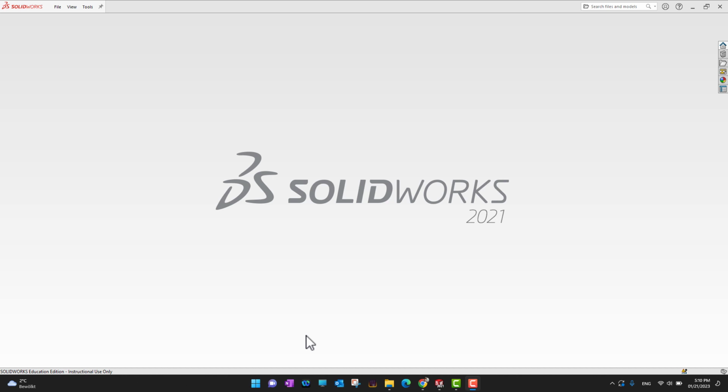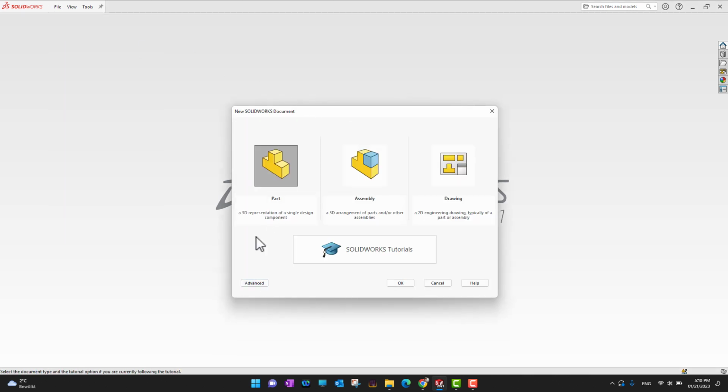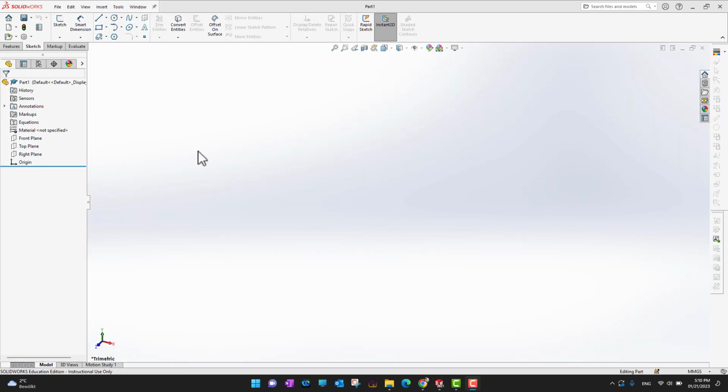Specifically in this video, we are going to design our first part. I'm going to go into SolidWorks and start with a new SolidWorks part. If you want to start from the part, you can click on New, and here you can select whether you want to start with a part, assembly or drawing. As in this video we are going to design our first part, I'm going to select Part and then press OK. Right now we are in the part environment.